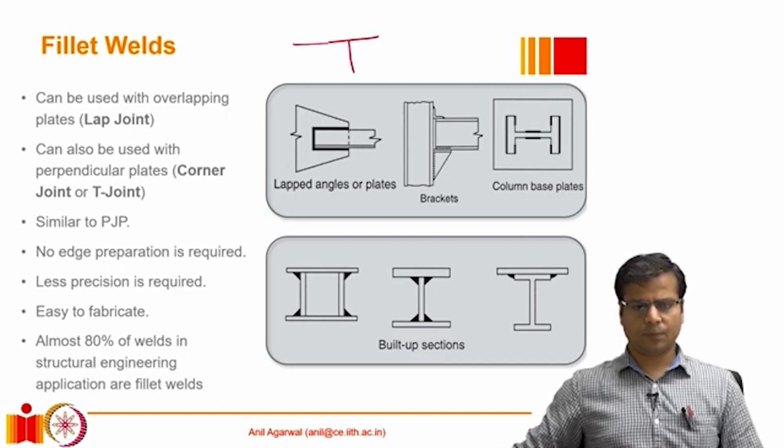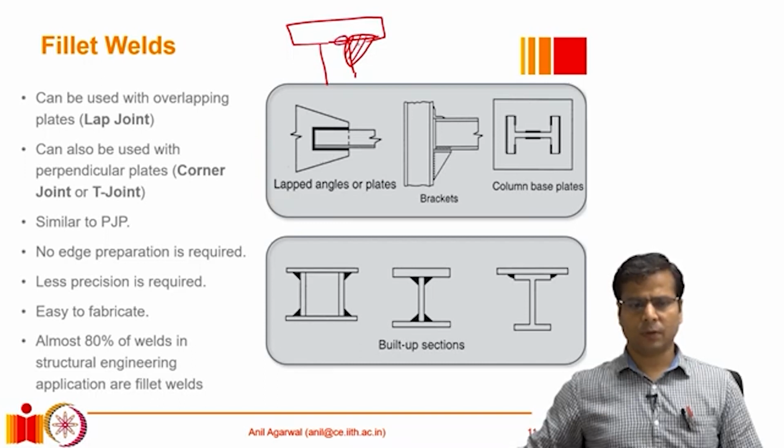So if this is one plate and this is another plate, and the two plates are being welded together, and we provide a fillet here, that fillet typically fuses this part of the two metals. However, in that process, these two metals get fused in this area, but right around this area, the two metals are not fused together. Okay.